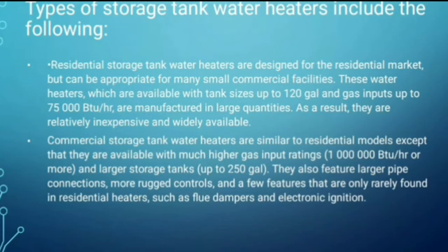Types of storage tank water heaters include the following. Residential storage tank water heaters are designed for the residential market but can be appropriate for many small commercial facilities. These water heaters, which are available with tank sizes up to 120 gallons and gas inputs up to 75,000 BTU per hour, are manufactured in large quantities. As a result, they are relatively inexpensive and widely available.